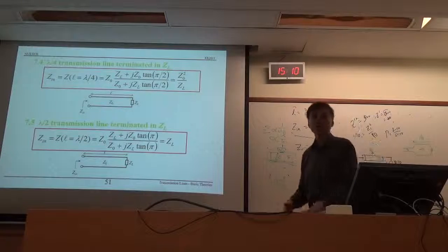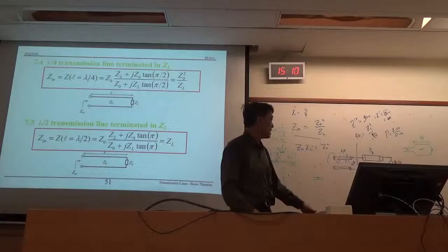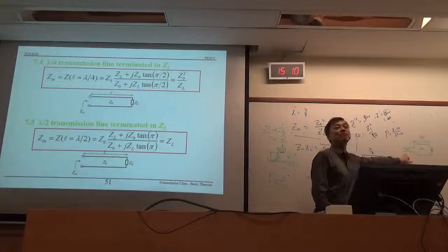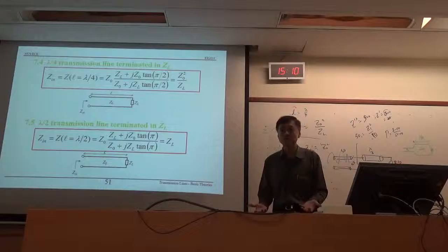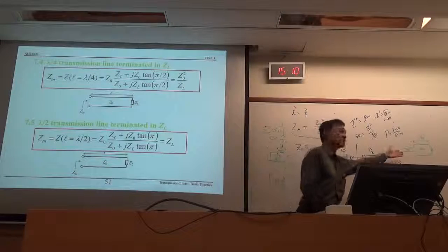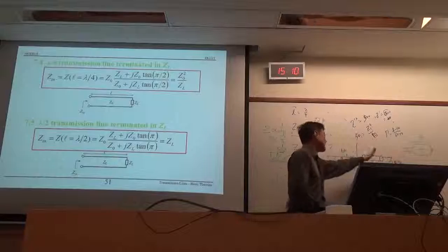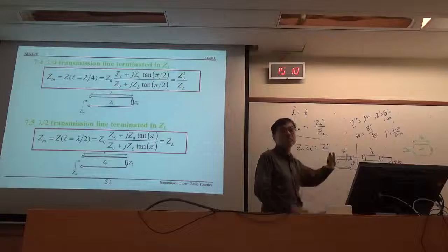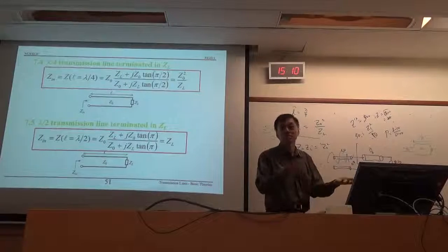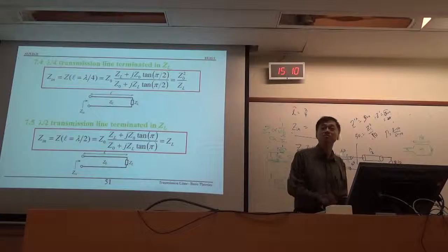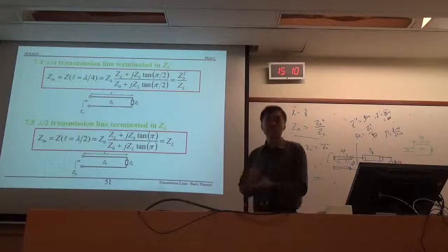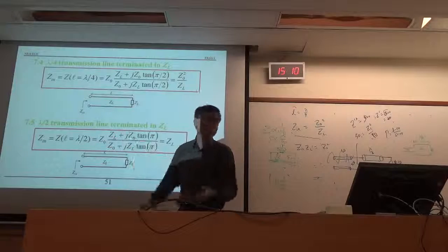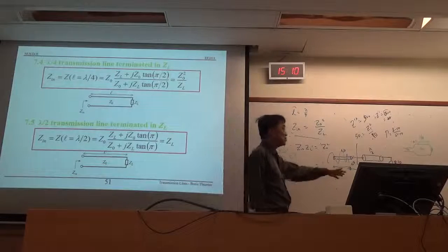Like that I can do my matching. I can have an 8 ohm load connected to a 50 ohm line without any reflection coefficient, without any standing wave in the circuit. Anything forwards, there will be no reflections and no standing wave. No standing wave is always good for a circuit. So this is another important result that you can use to do matching.